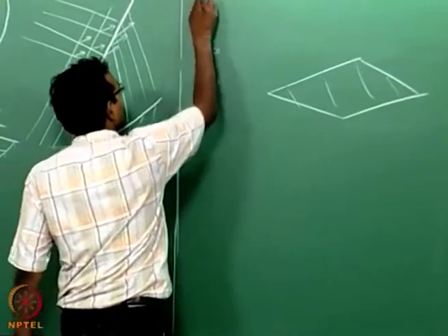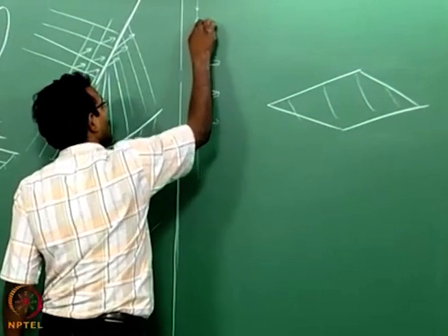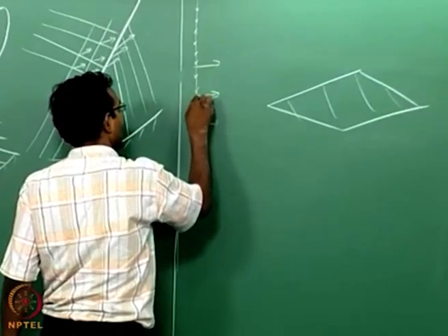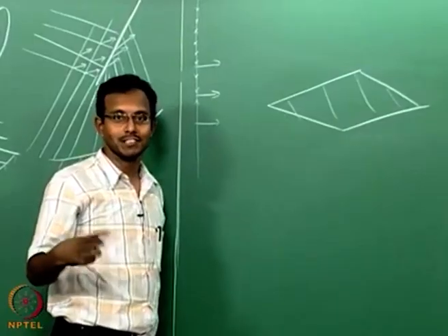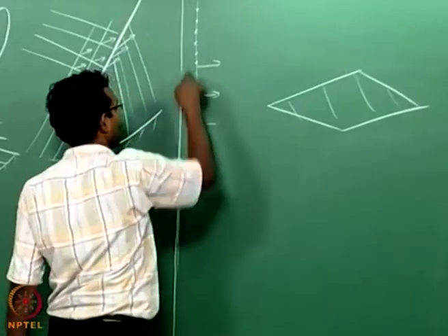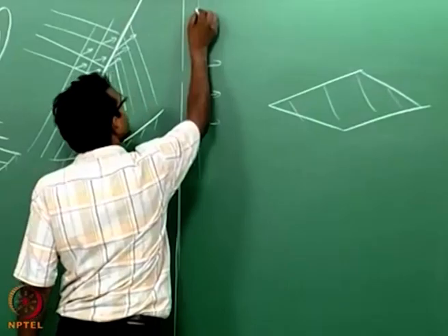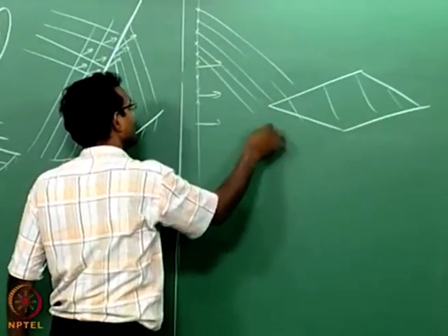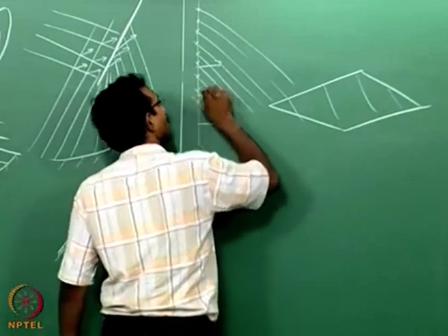So I can pick a set of points at some condition and say I know the location of the points because I pick the points, and at all those points I am going to tell the Mach number and theta, right. That is what we need for every characteristic point. I need x, y, theta and Mach number. So I will give all those for all these points. I just distribute a set of points here. Now all I have to do is start running characteristics from them. I just have to start running characteristics from there in positive and negative directions.